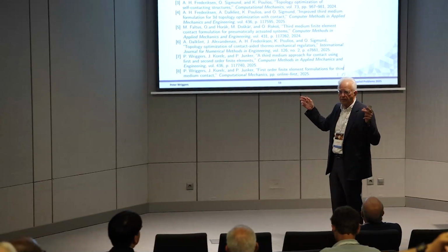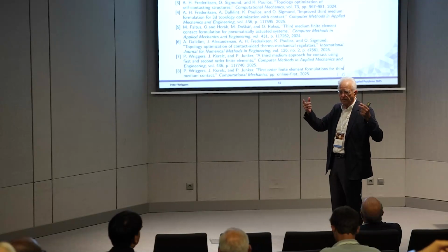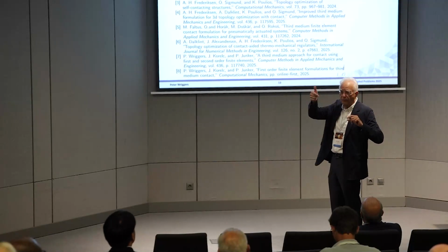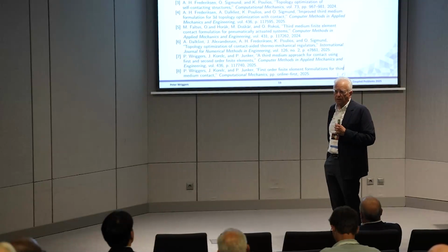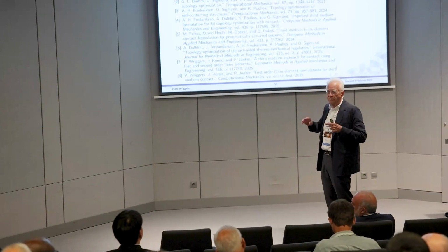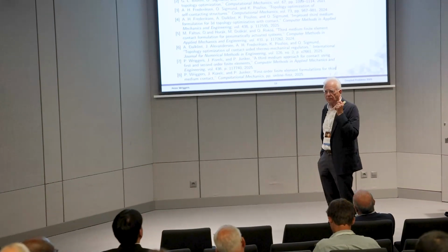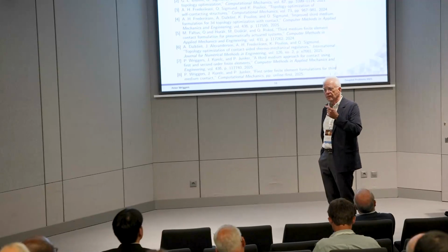In contact mechanics, you have this barrier method as well, which is like the reverse of the penalty method. You don't have a Lagrange multiplier here, and the regularization parameter is something different. It looks a little bit like an augmented Lagrangian type of technique, but it has nothing to do with that. It's only for the control of the shape of the element.